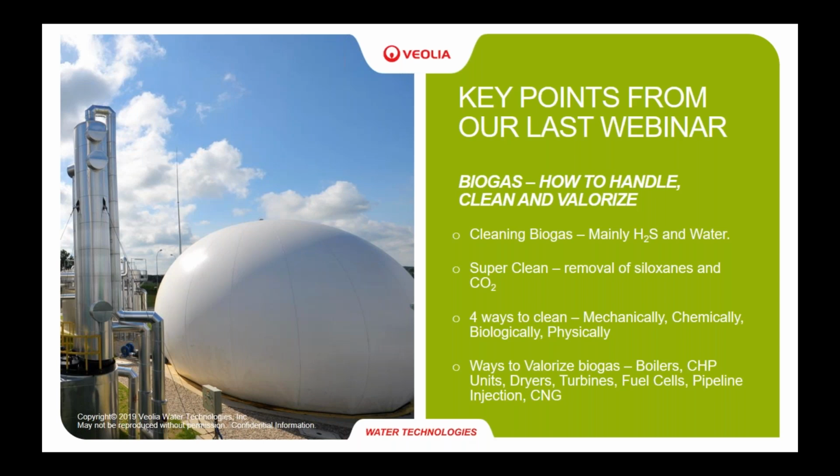And the big thing is how you're going to use the gas once you've cleaned it. The easiest way, and what was mostly done here in the United States, is to feed it back into a production facility's boiler or in a local boiler at the wastewater treatment plant to heat the wastewater. More and more we're seeing combined heat and power units where the biogas is used to generate heat required by the system and power so you can run your plant with the gas you're generating. There's also dryers that it can be used in, turbines, fuel cells and pipeline injection and CNG.